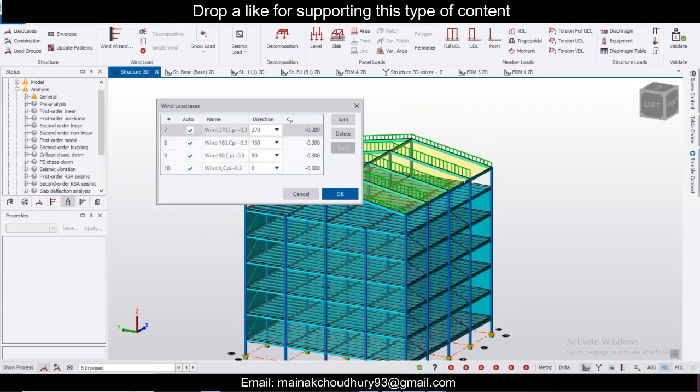Now we'll change the CP values. So now see, along the x is along this direction. So 0 means along the x. Okay, so along the x the CP value is 0.8. Okay, so along the negative x direction we know that is along the windward side, if it is 0.8, then along the leeward side, that is at 180 degree, it will be 0.5. So let's do this 0.5.